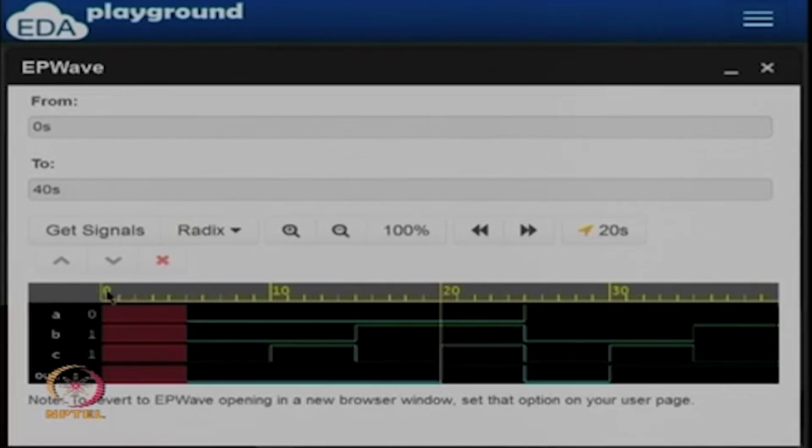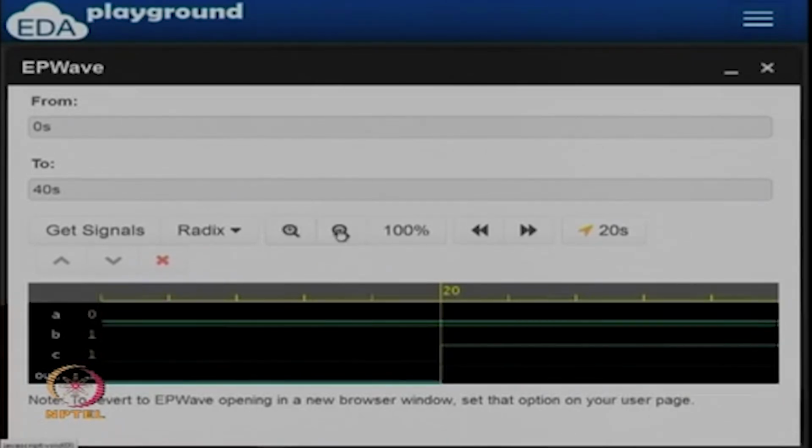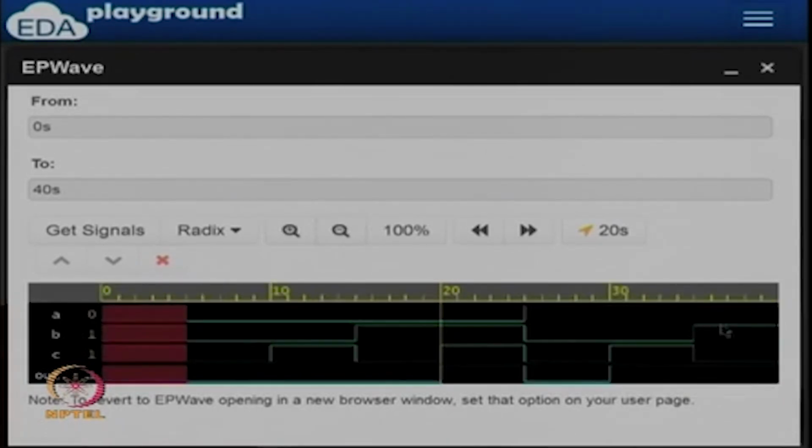You can see that in the waveform viewer, time is on the x axis, and on the y axis you see various signals, and for every signal you can see the time frame. So what are the values of different signals at different points of time, right, and you can zoom in, zoom out and so on. If you want to zoom in and see something, you can, or you can zoom out. In this case the whole waveform fits here, so there is no more zooming out, we can see all of this design fit into this particular view.